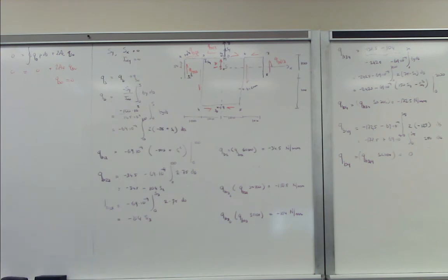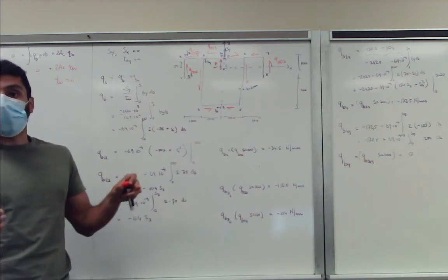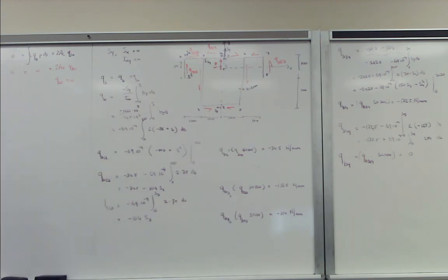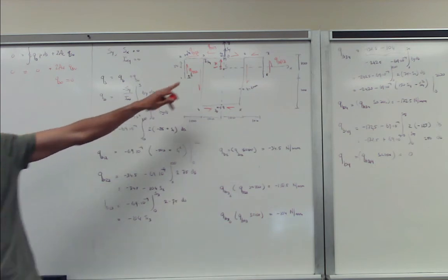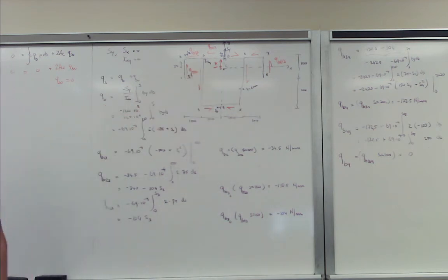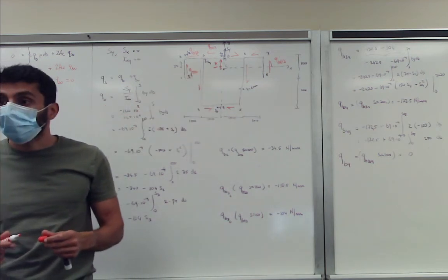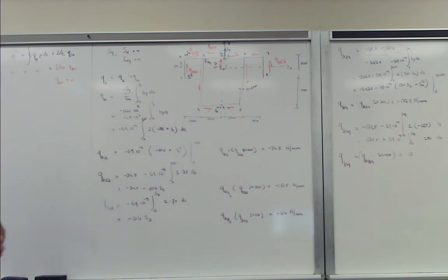And in many cases, you will look at this cross section. You can basically determine a very convenient point where you only have to do just one shear flow and one moment arm, or you can actually determine that it's equal to 0 without doing any calculations. So that's why we chose the cut at 0, because it conveniently gets rid of those two.